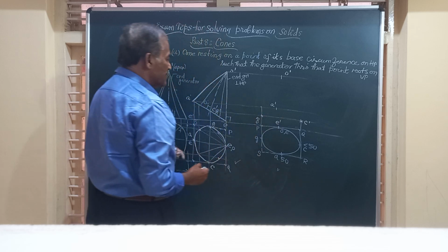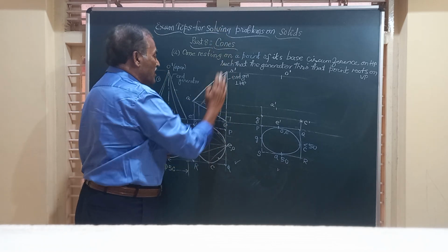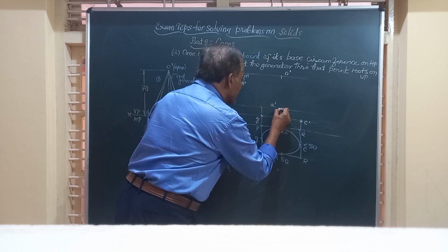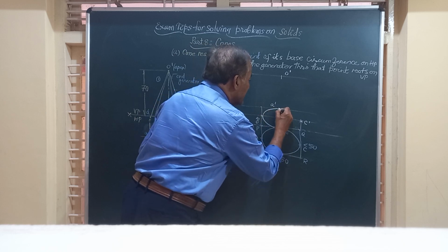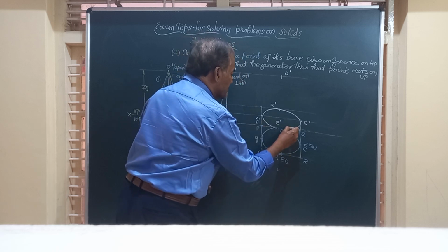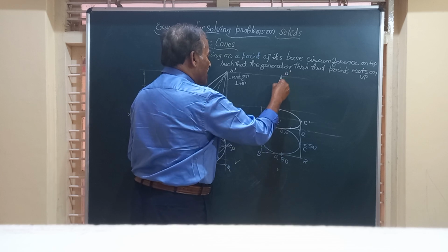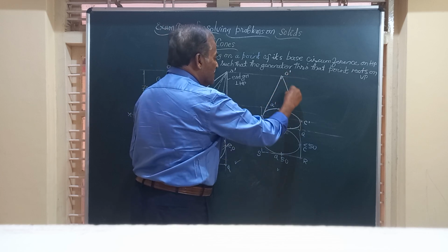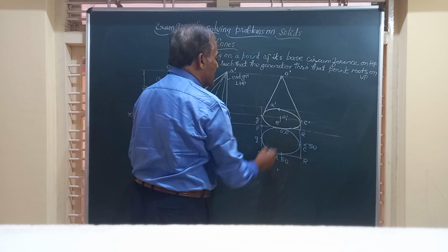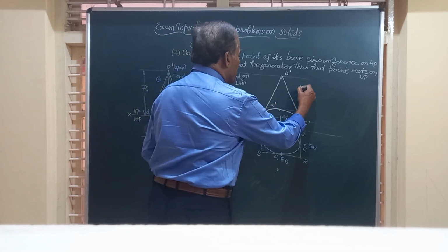And friends, since this end generator is touching the wall, you will be able to see the complete base. That's going to be an ellipse again. Complete ellipse of the solid is seen in the front view. And friends, from here, draw tangents to this, and the midpoint of that is O1 dash. Friends, this is how the front view of the solid looks.